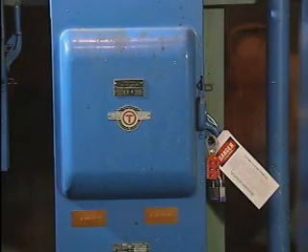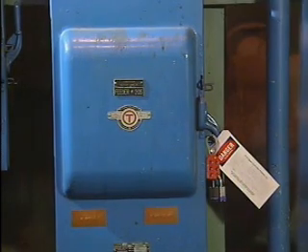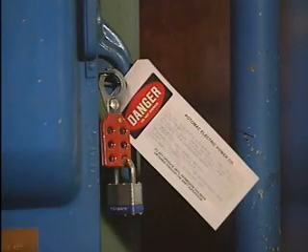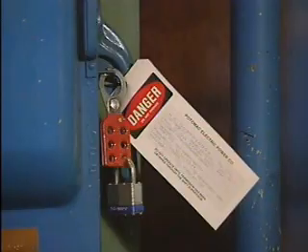An effective lockout and tagout procedure describes the steps that are necessary to make sure that equipment is shut down and isolated from energy sources such as electrical power. The procedure is designed to make sure that equipment is safe to work on. The term lockout refers to the use of locks or similar devices on deactivated equipment, such as electrical circuit breakers. The lock actively prevents the passage of energy from a source to the equipment being worked on.